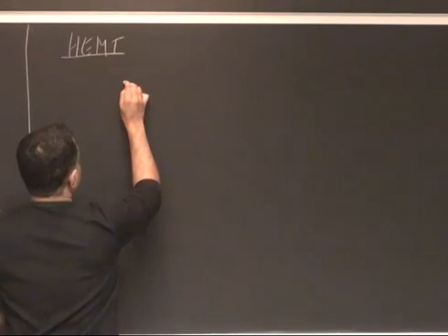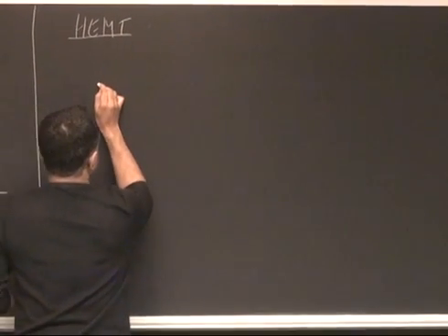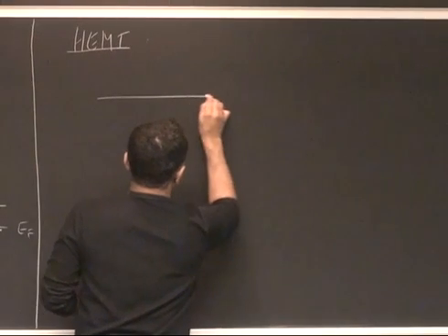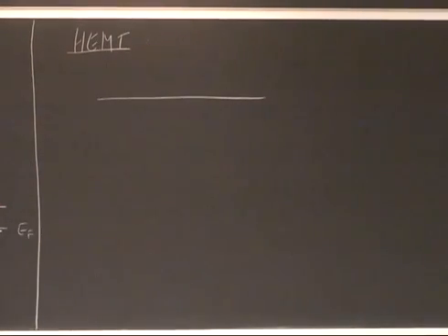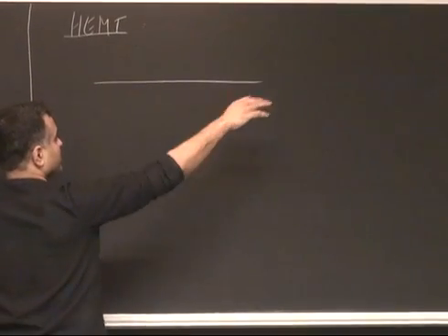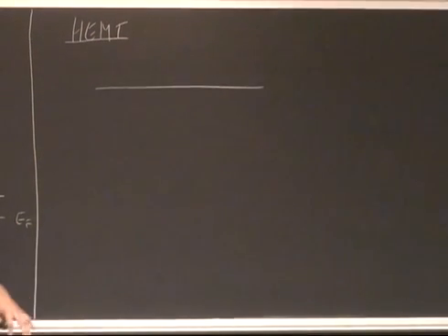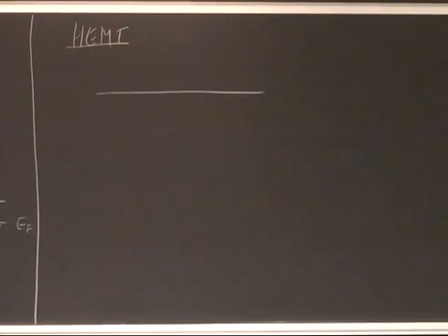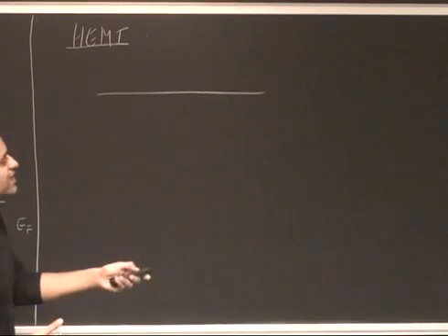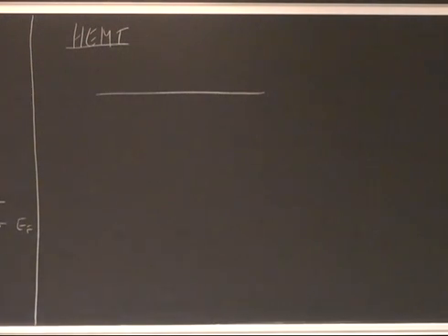Okay. Here, the layer structure is what you get when you grow it epitaxially. Let me go through the process of what one would do. You typically first design it, using your band diagrams and all that, and say, I want this thickness, I want this quantum well there, I want this many electrons in that quantum well, maybe I want just two subbands, two quantized states or something like that. You design it first, and then you grow it.